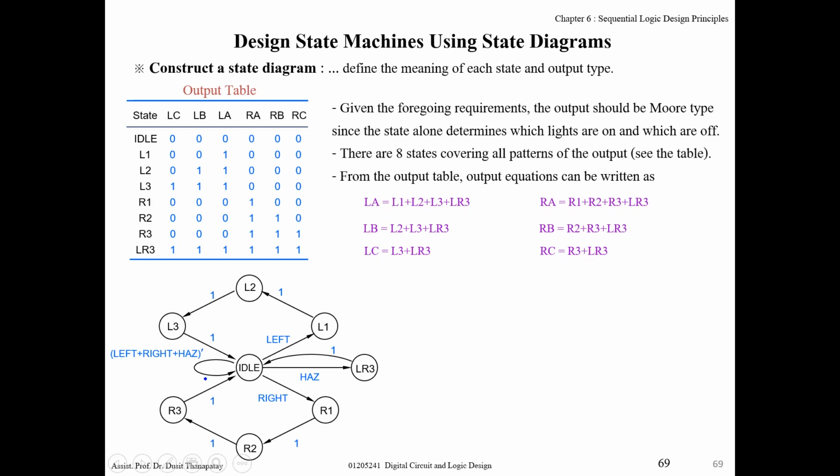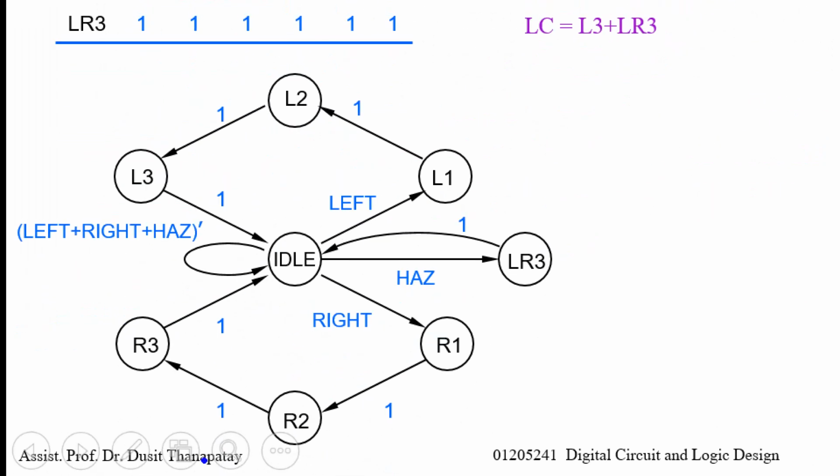When you write a state diagram, you should check whether it's correct or not, by using the principle of mutual exclusion and inclusion. For example, at state idle, because in this system there are 3 inputs, you should check that all inputs have a next state, and have only one next state.